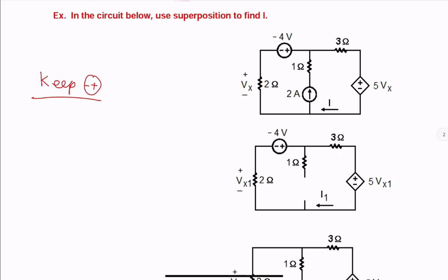Looking at that circuit, the current I1 is at the bottom and it's going clockwise. Let us write Kirchhoff's voltage law for the outer loop. First term is positive 2I1. Don't pay attention to the polarity of Vx1. We're looking at voltage drop across the resistors using passive sign convention. And I have described that in my examples and videos for mesh analysis. If you have not seen that, go and review those.